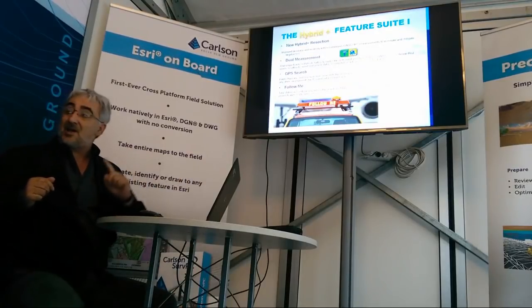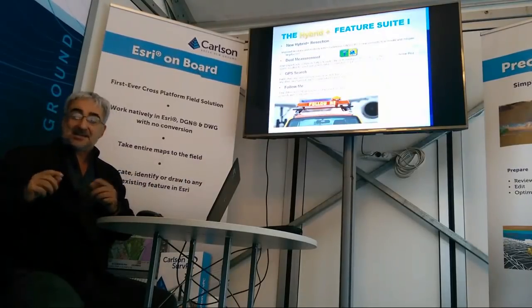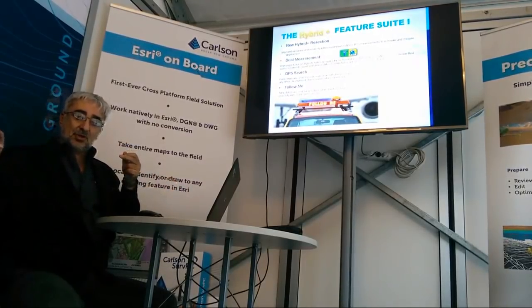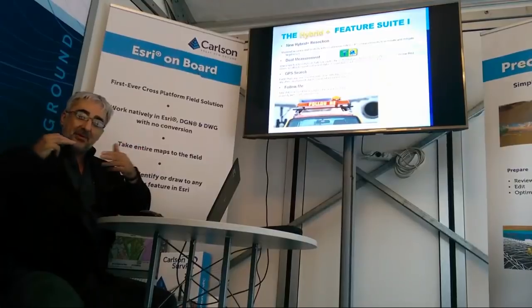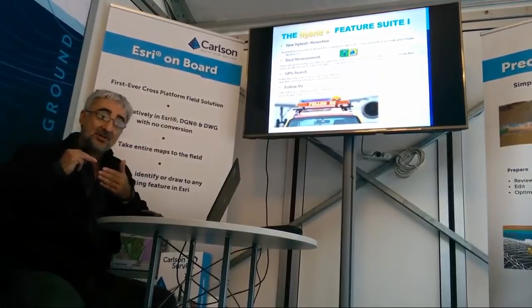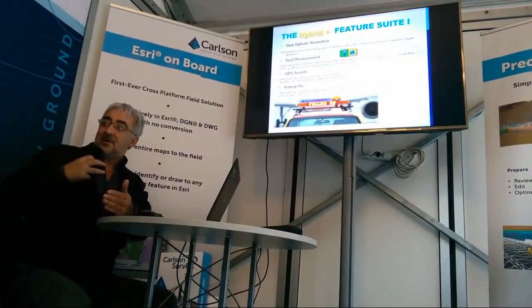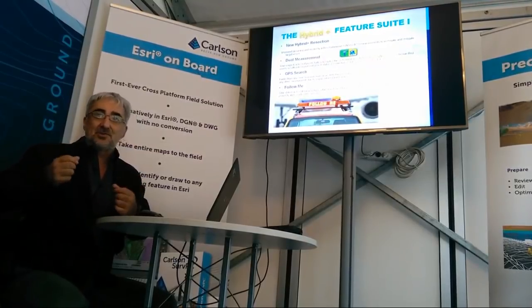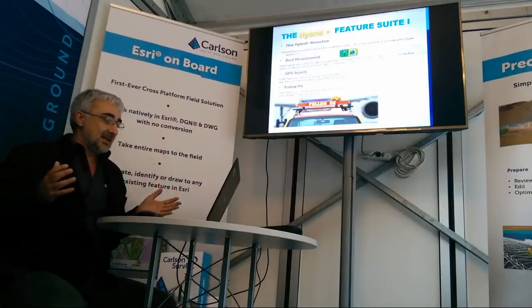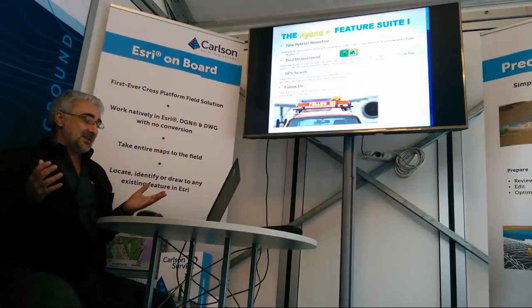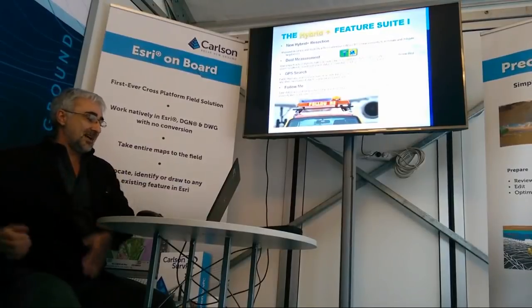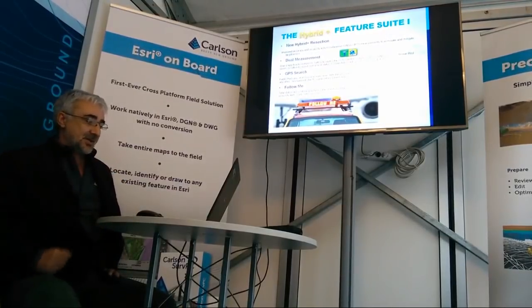And there is a hybrid tolerance. You can say, okay, if the GPS shot and the total station shot differ by more than 2 centimeters horizontally, please warn me, right? That is my tolerance. So it will warn you when GPS is doing weird things because you're in multipath, or this or that. You can get confidence that you're doing a good job all the time, right? So we have this cross check too.